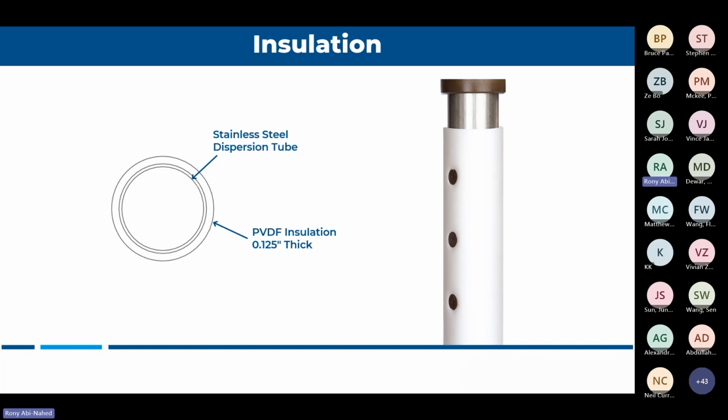But why don't I recommend the brands that don't have the stainless steel? Because this insulation, if it's not protected, with time, it will dry off. It's like in the airstream, it will dry off. You'll always have some water dripping from here. So the water at some point will come perforate your insulation, and the insulation will start flying into your airstream. So if it's not protected, after 5-6 years, you check your insulation, you barely have any insulation left. So ideally, you always need to protect your insulation.